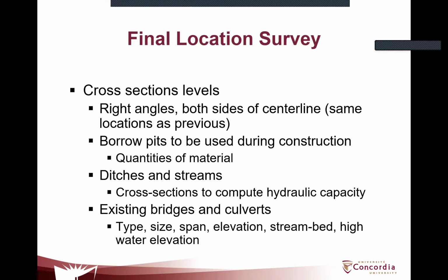Once you are dealing with the earthworks, then you have to locate where you have borrow pits that you can take material from and where you have landfills where you can dispose of the vegetable coverage and some of the trees and bushes that you might need to cut, or material that you need to discard.